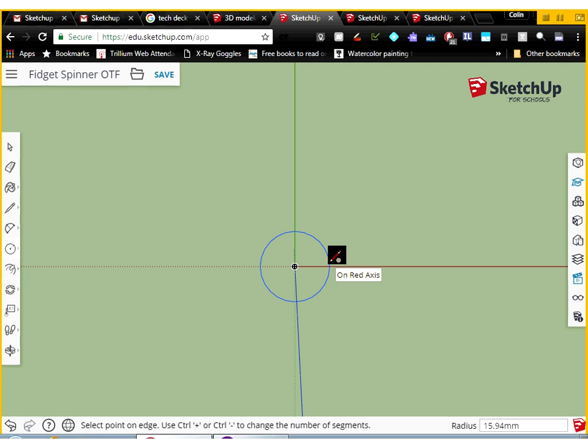And the second thing that I have to remember here, and I apologize to teachers in the junior classes, is that I have to be aware of some terms when it has to do with circles. The one that I'm actually drawing in is the radius. That's my line that goes from the center point of the circle to somewhere on the outside. So if I need a circle that is 22 millimeters across, then my radius has to be 11 millimeters. In this case, I want it to be a little bit bigger, so I'm going to make it 11.1.